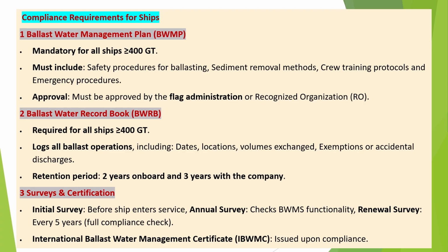3. Surveys and certification. Initial survey, before the ship enters service; annual survey, checks BWMS functionality; renewal survey, every 5 years, full compliance check. International Ballast Water Management Certificate, IBWMC, issued upon compliance.